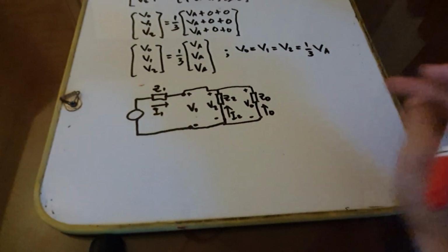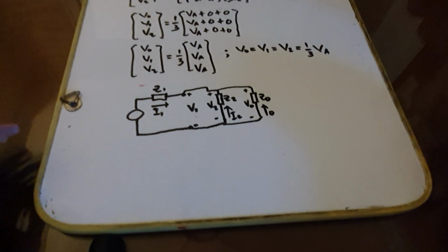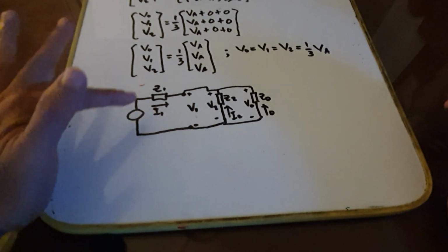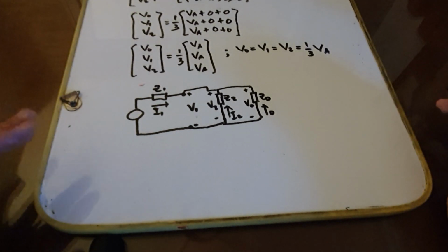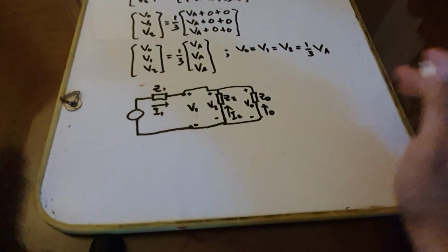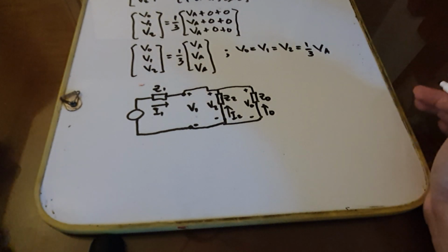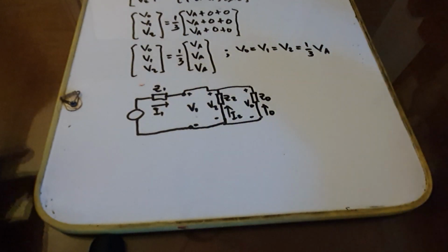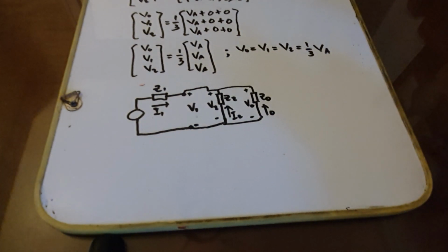Next we are going to derive the formula, because we are going to calculate the sequence currents. Then after that, we will use the phase currents in the symmetrical components to determine the phase currents during the one line open.